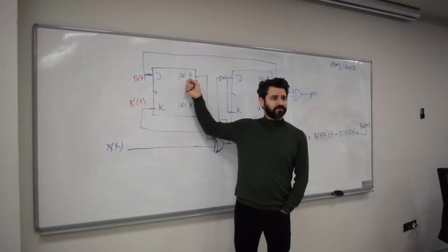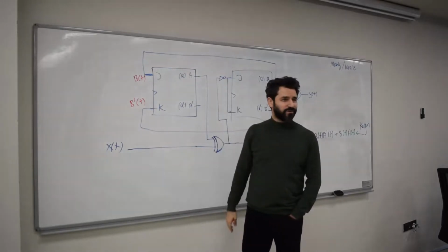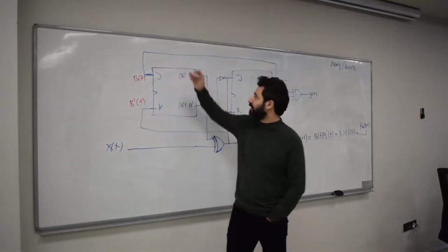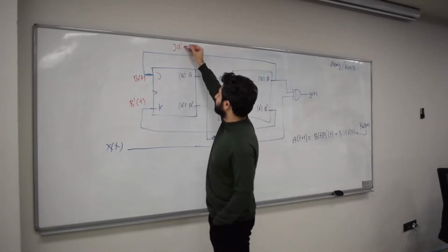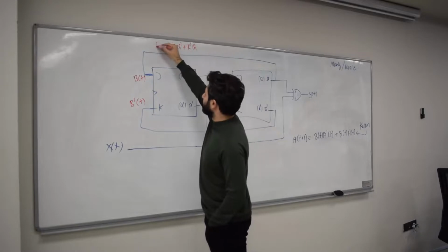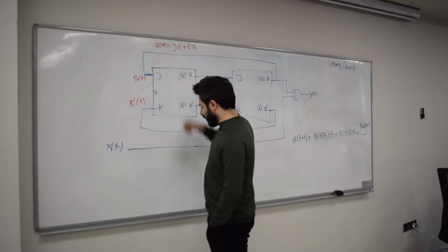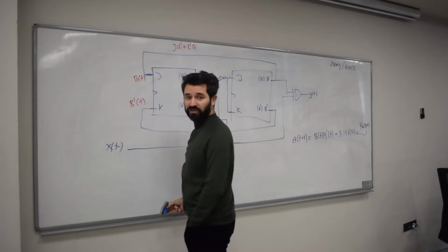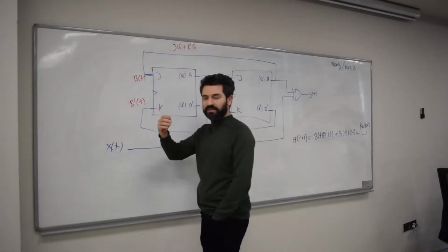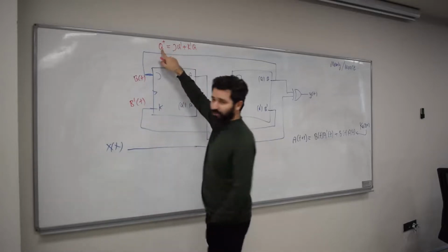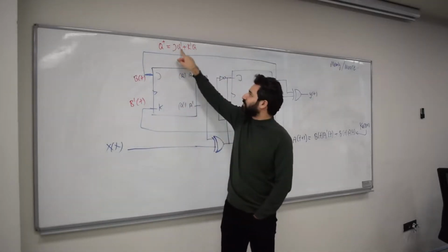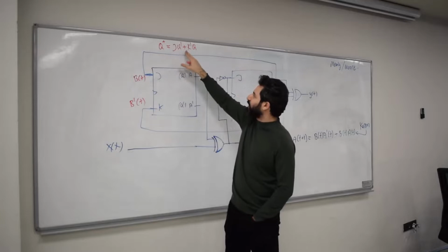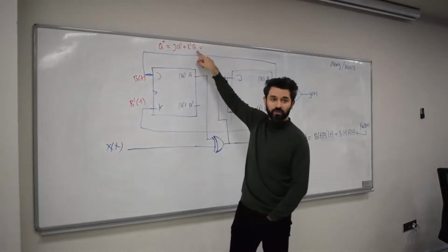Remember that? What is that? Can you tell me, from your notes, what's the relationship between inputs and the output of a JK flip-flop? Q(t+1) equals J Q'(t) plus K' Q(t). Yes. Since I didn't put t's here, sometimes I use Q plus, and some literature does that as well, to indicate the next state. So Q+ equals JQ' plus K'Q, which is actually t+1. Sometimes people don't put t's because it complicates everything. That's the relationship. You don't need to memorize it, by the way.